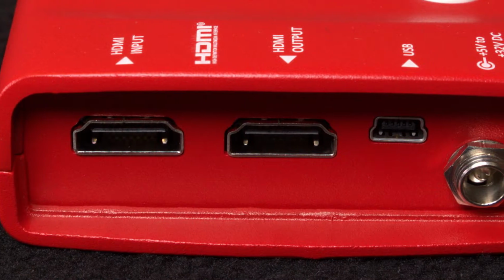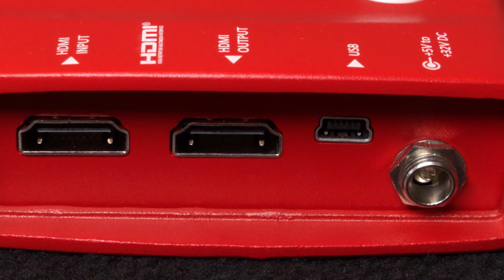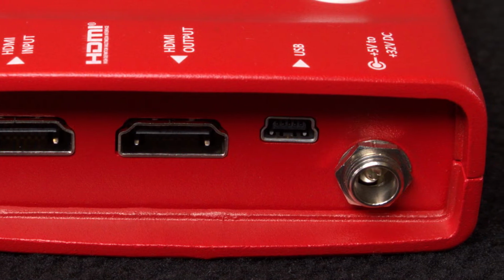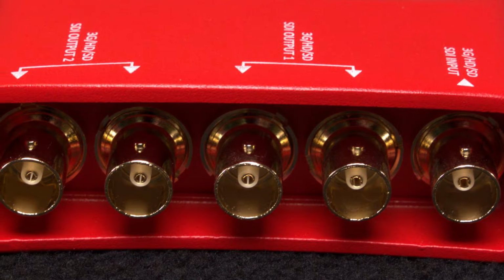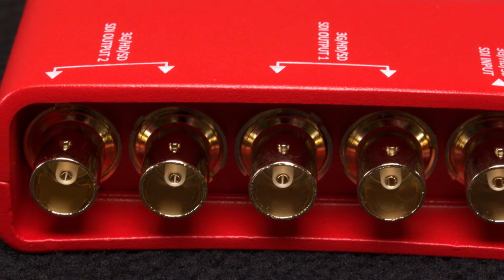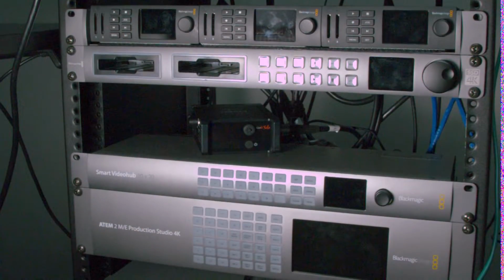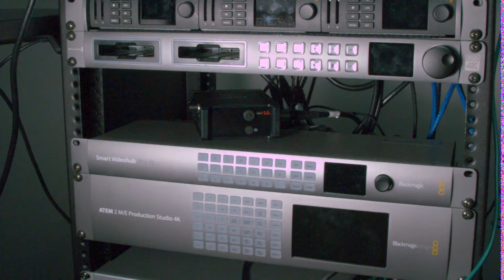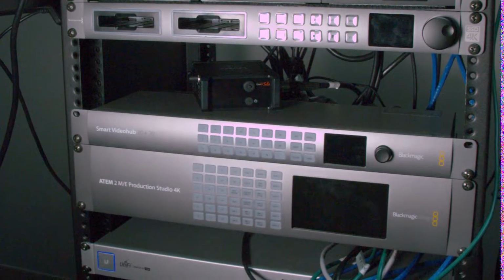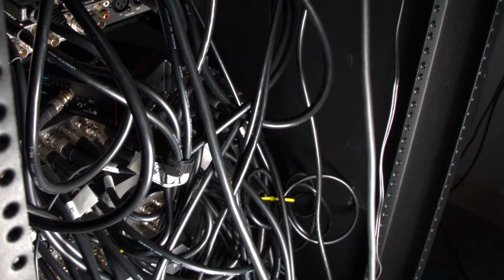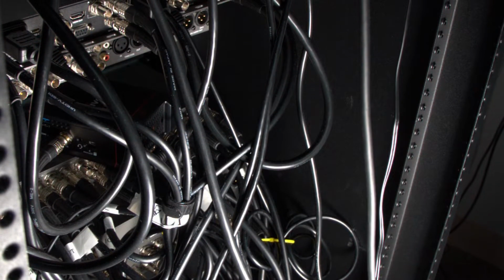The Decimator actually has several functions it can perform, but we are using it to code and format the SDI signal, as well as communicate the digital information to the hub. The hub does not perform any conversions or scaling. It is simply there to route the AV signal to one or more destinations of our choosing, such as the HyperDeck digital video recorders or one of several monitors.